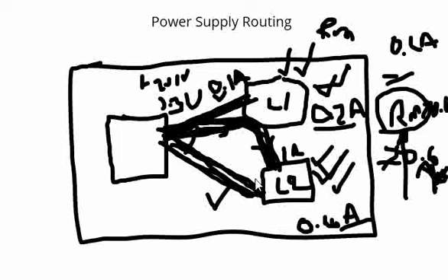and you did the routing in a different way to avoid the voltage drop across the traces, please do post in the comments. Most of the people, if you observe, prefer to do a star routing in the case of low layer boards to avoid such scenarios.